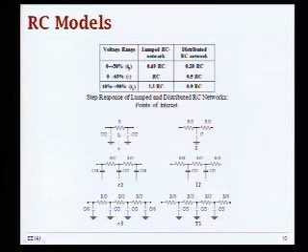So when I break up my wire, I can take segments that correspond to this model. And this basically captures many of these RC segments that we talked about with the slide about the diffusion equation. When you divide up a wire into really small segments, you maybe take a good number of segments and say, well, this is my sort of crude model for that schematic.